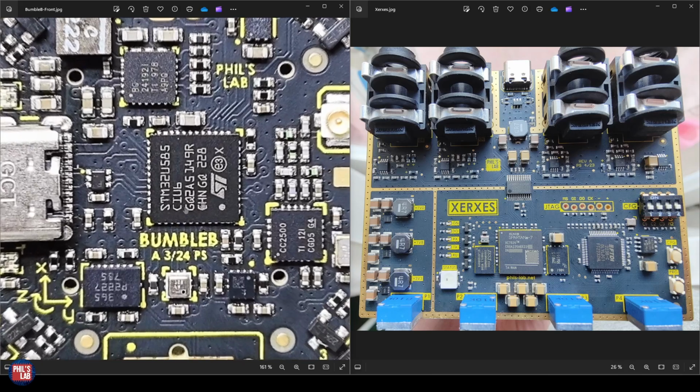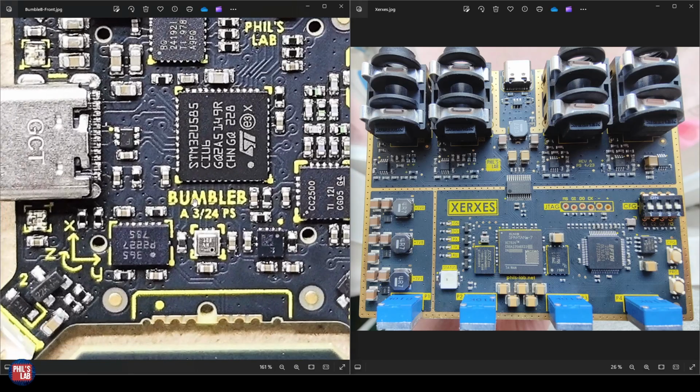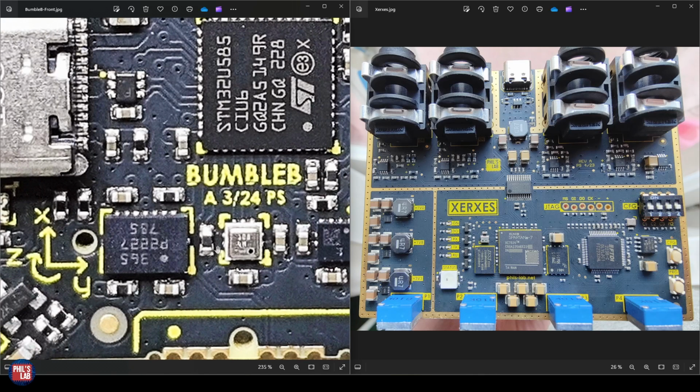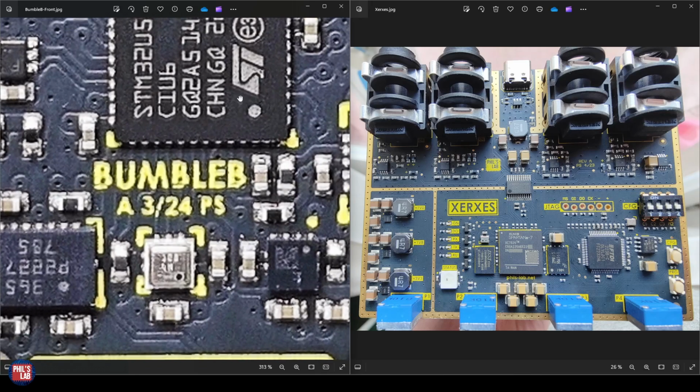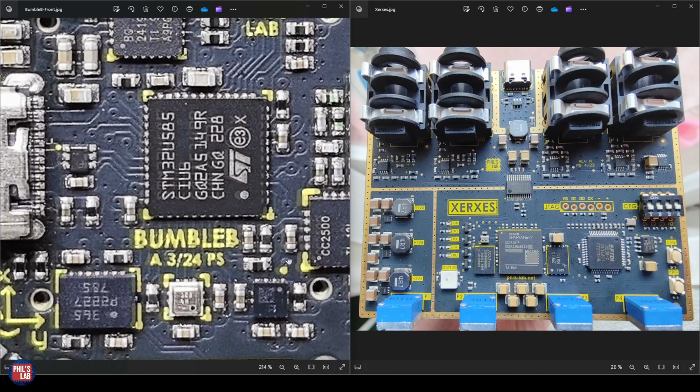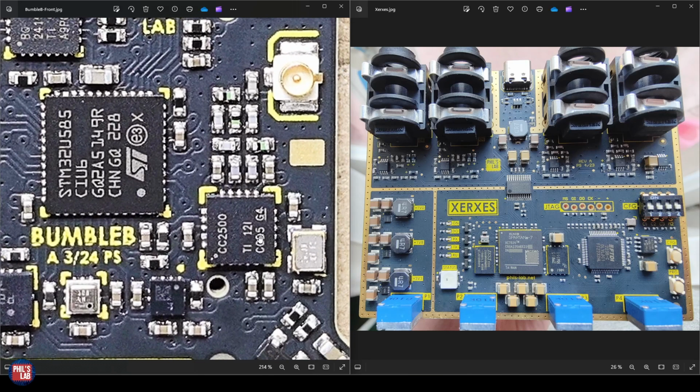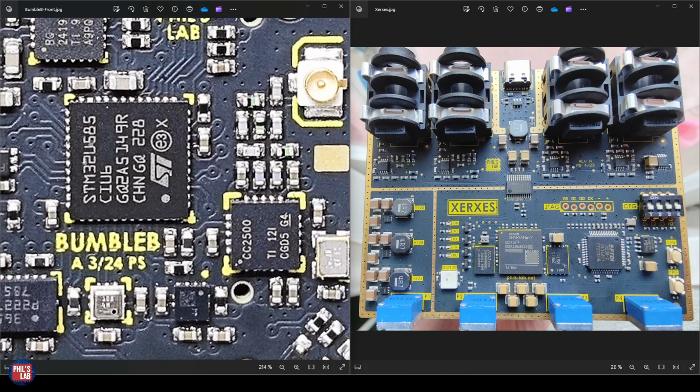But for example, also this STM32U5 microcontroller in the center, which interfaces, for example, to the bottom left, to this inertial measurement unit via Serial Peripheral Interface, or SPI for short, transferring data to and from the sensor. Similarly, also the barometer, which transfers pressure data and pressure measurements back to the host controller via SPI, and for example, this CC2500 RF transceiver, which I can use to communicate, for example, with a base station. The interface between the controller, this STM32U5, and the peripheral is via SPI.